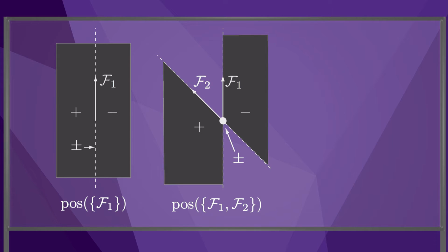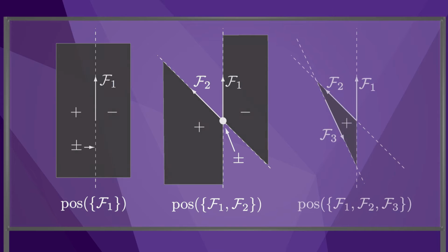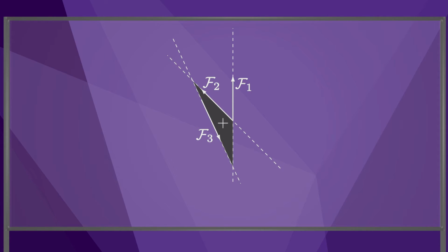This cone could be viewed as the wrench cone for a single frictional contact. These moment labels are properly interpreted as a single convex connected region. As with the rotation center representation, the plus and minus regions are connected at infinity. If we add a third wrench, F3, then the consistently labeled region is just a small triangle labeled plus. This representation means that the positive span of the three wrenches can create any line of force that passes in a counterclockwise direction about the triangle.